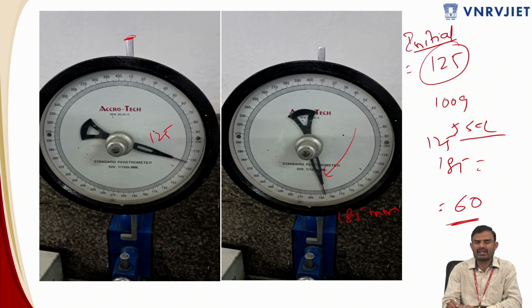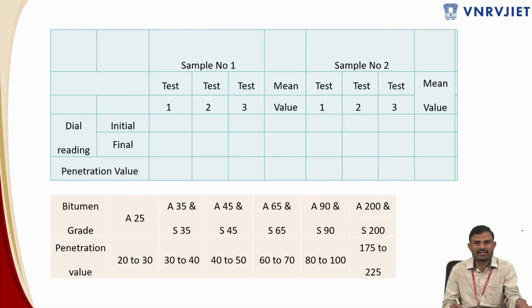The units are 1/10 of a mm, or 0.1 mm. If you want to convert this into mm, 60 would be 6 mm. Sorry, 60 tenths of a mm is 6 mm, so that is the penetration value. This is how you conduct the test.